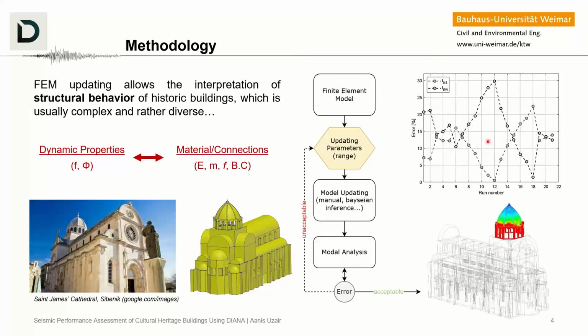But because you are basing this on a particular measure of error, and because you are comparing everything with an eigenvalue analysis, everything that you are doing at this point is in the linear elastic domain. That means that all the nonlinear properties that you consider later on have nothing to do with the finite element model updating, and those properties might or might not represent the nonlinearity of the actual structural system.